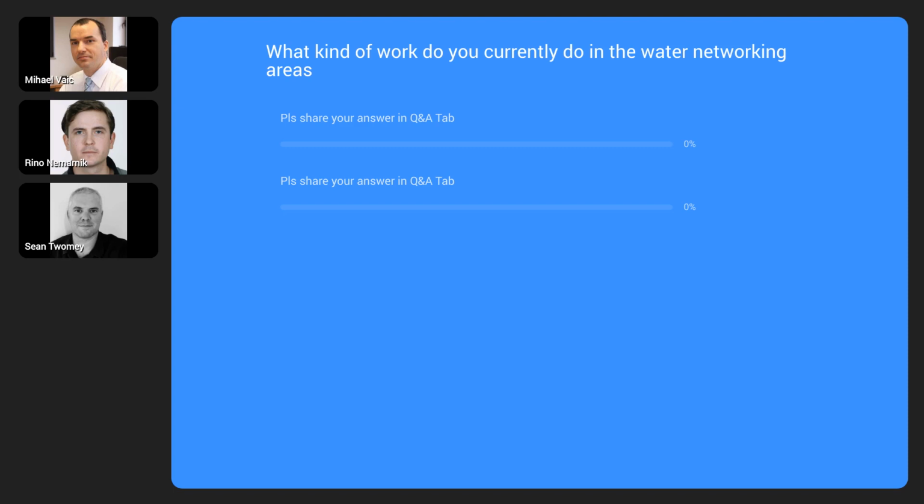So regarding all the equations, it is done like in EPANET, and in the options dialog you have the possibility to choose between 3 different head loss formulas: Hazen-Williams, Chezy-Manning, or Darcy-Weisbach. That would be the shortest answer. Yeah, that's a pretty complete set of offerings.